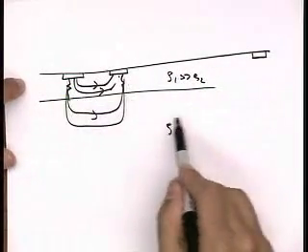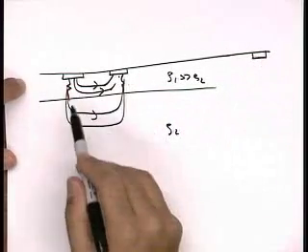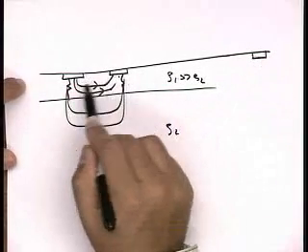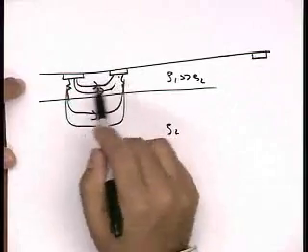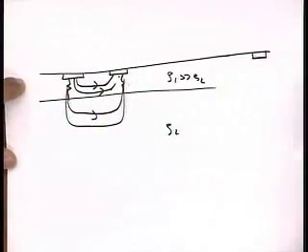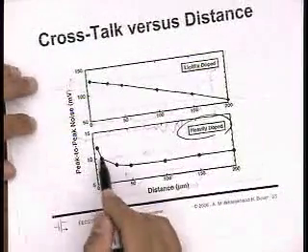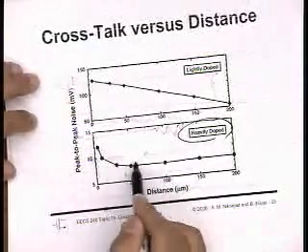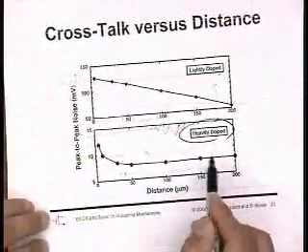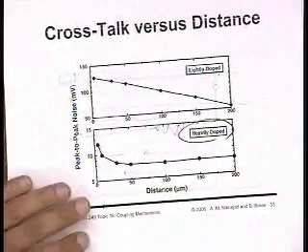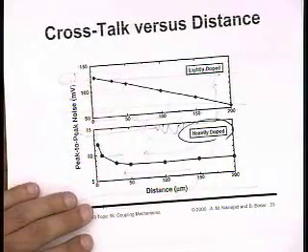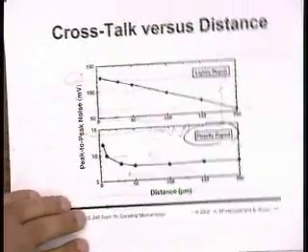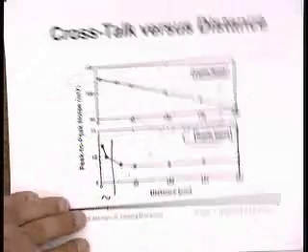So most of the current will flow through the body, the bulk. But for very close distances, it's the epi that's contributing. And so if the epi is contributing, getting far away does help. Initially there is some help, but then it's all the body that takes over. So I guess the thickness of the epi really counts for that kind of thing, right? Exactly. So this distance is on the order of the epi thickness.